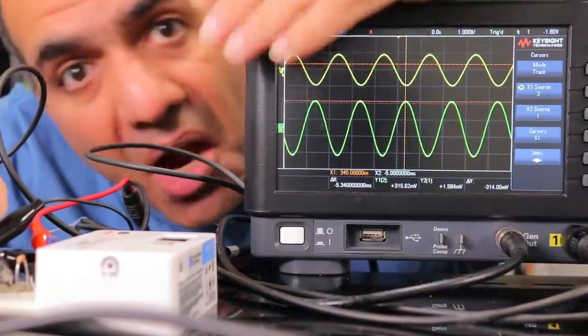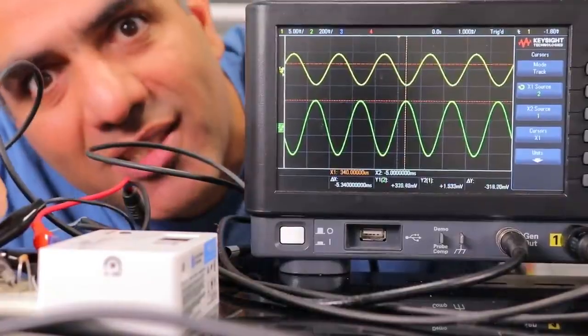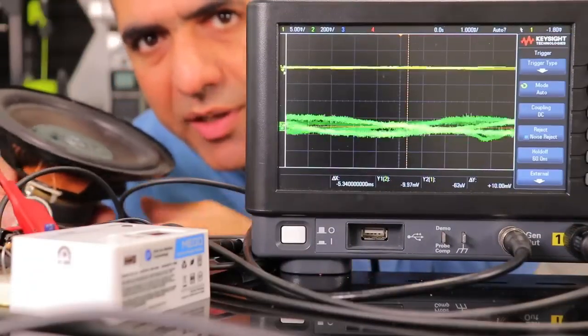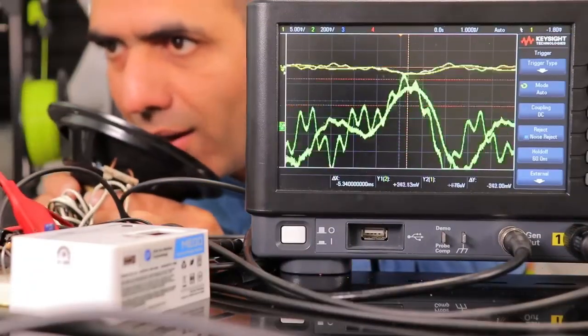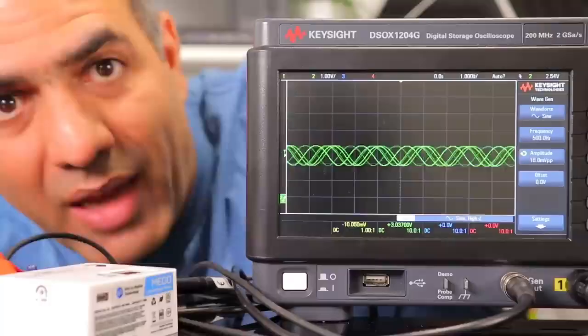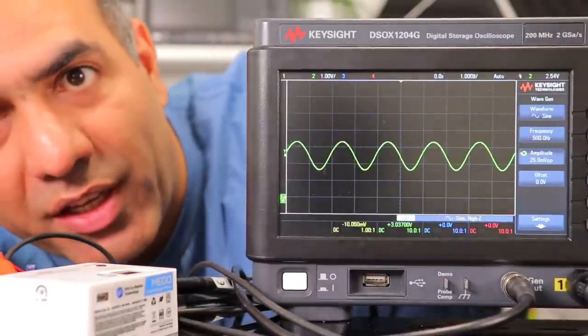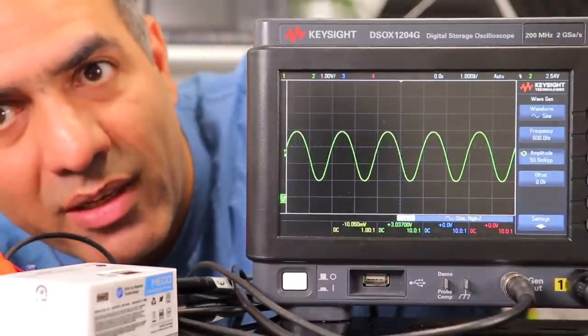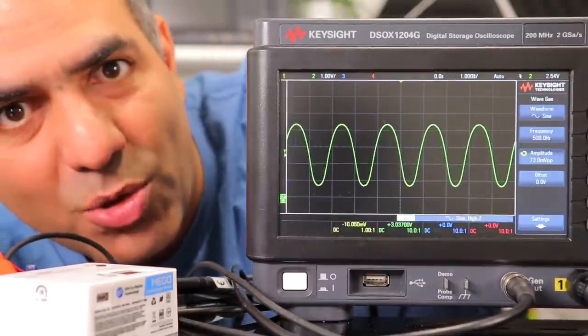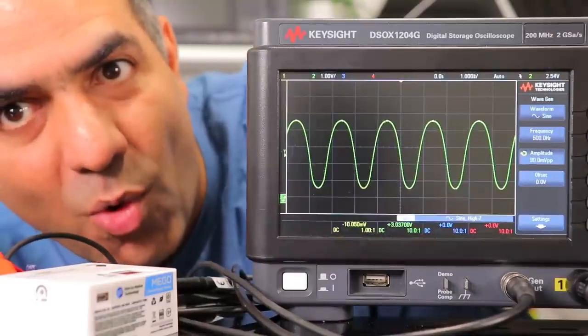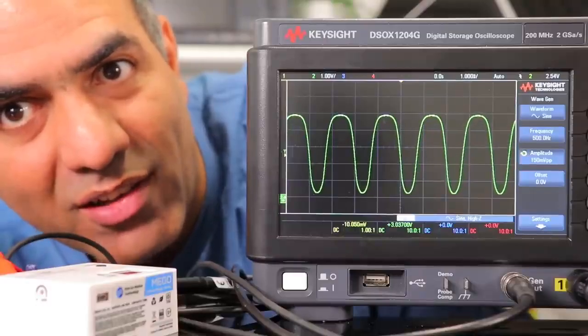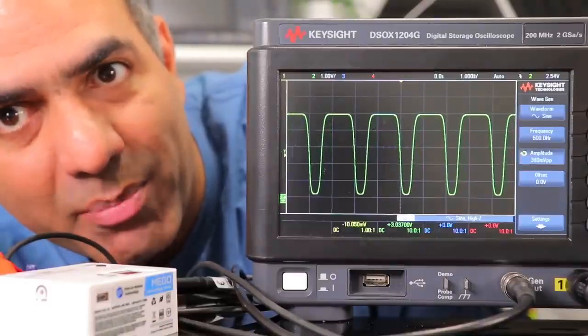I could connect a microphone to it and amplify my voice. Well, I'm using a subwoofer speaker as my microphone. Ella, Ella, umbrella. Now only looking at the output voltage, if I increase the input, you see we start seeing the distortion I was talking about more and more until the signal hits the rails and clips.